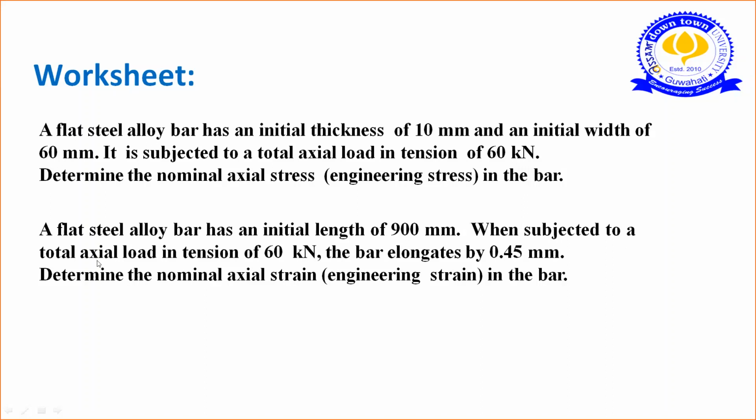And another question is, a flat steel alloy bar has an initial length of 900 mm. When subjected to a total axial load in tension of 60 kN, the bar elongated by 0.45 mm. So determine the nominal axial strain or engineering strain in the bar. Please do this numerical and let me know the answer.